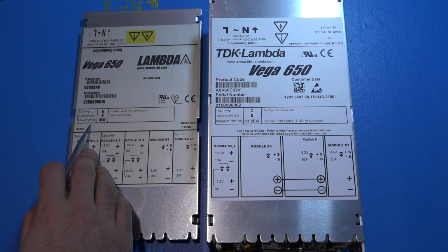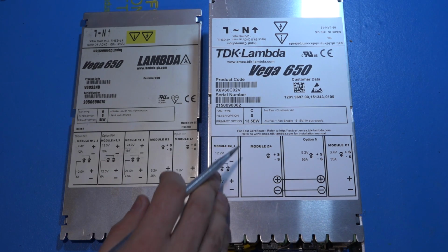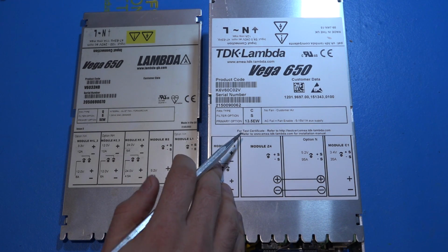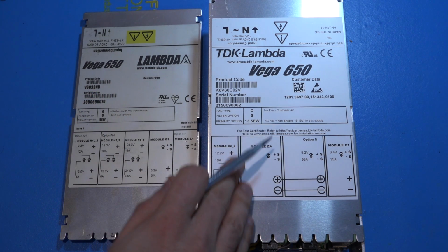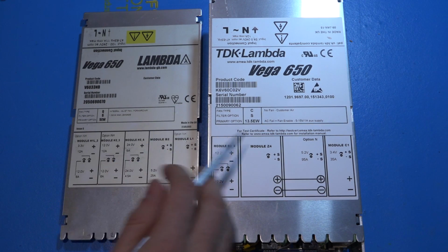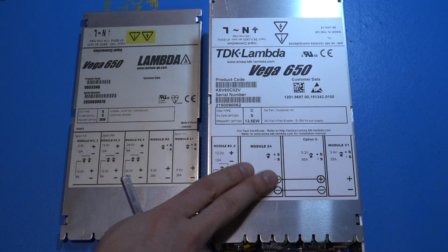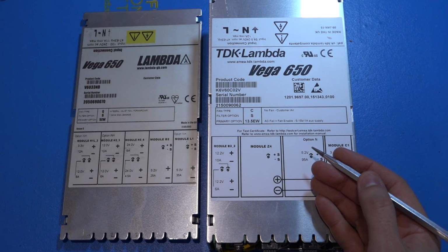Now, this one has a primary auxiliary voltage of 5 volts, and this one has a primary auxiliary voltage of 13.5. So the primary side circuitry is not suitable as it is to be used in here. We have to open this up, find out if the primary option card is interchangeable between these models. Now, this is supposed to be a working power supply. I haven't tested it, but we can easily find out once we open it up.